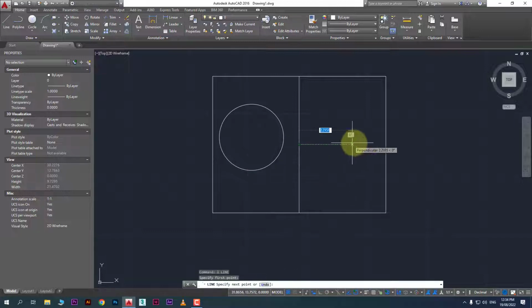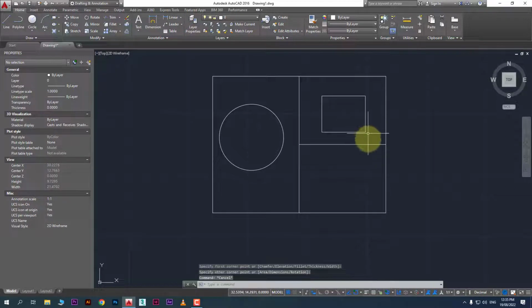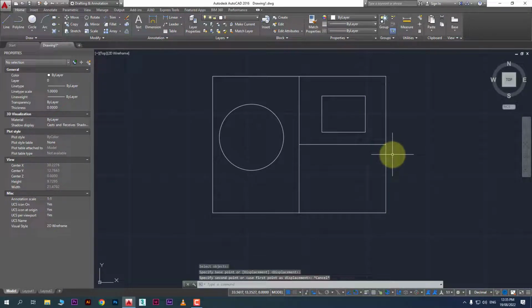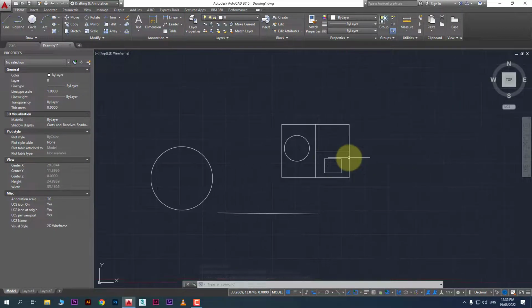Same for example, if you have mid to mid here, and you have one object here, REC for rectangle, and you want to move equally here, you use the Move command M and select the object, and it also depends on where you are picking the object from. If you are picking from the corner here, you cannot place it at an accurate position. So you have to look for the common base point in the 2 boxes. So Move M and enter, select the object and click on this. It's a common base point. Click here and you can just move it like this. That's why the base point is very important and we use it a lot of the time.